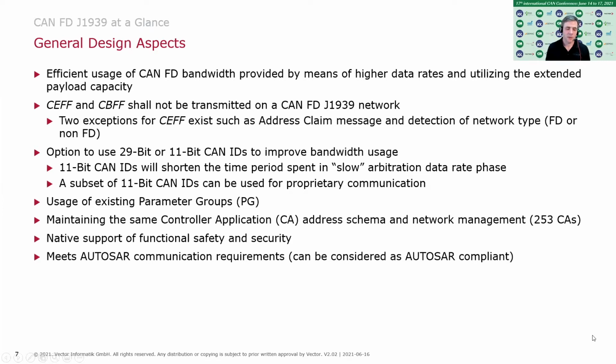The new CAN-FD J1939 approach fits into the AUTOSAR communication requirements. In other words, if you are using AUTOSAR as the way to model and create your software, then you can, just by configuration, use this AUTOSAR stack to do the CAN-FD. There are exceptions. For the transport protocols, we will learn about those later. You need additional modules, which need to be supported by your AUTOSAR stack provider.